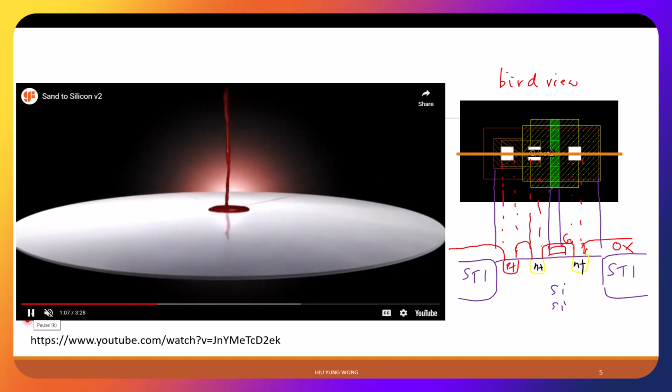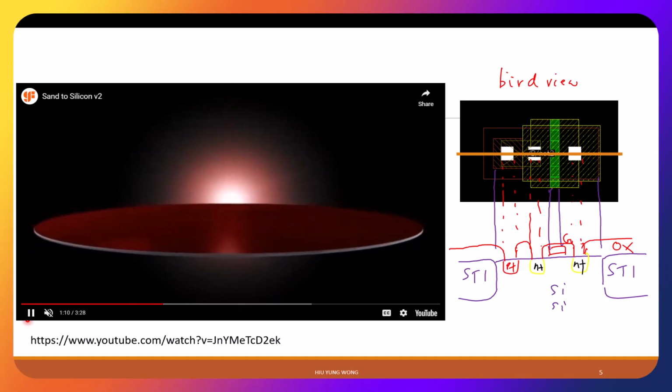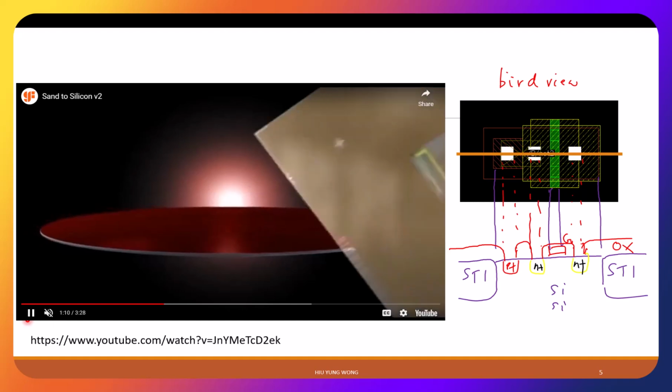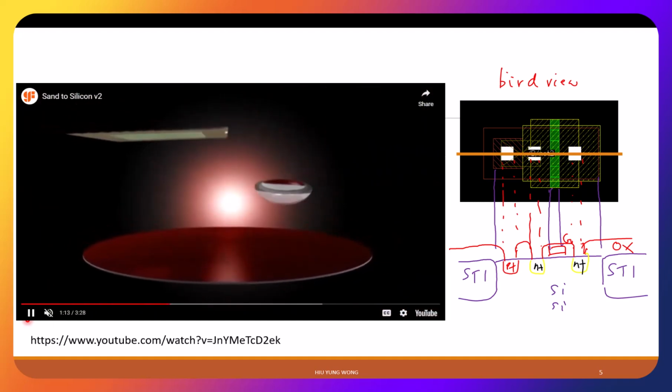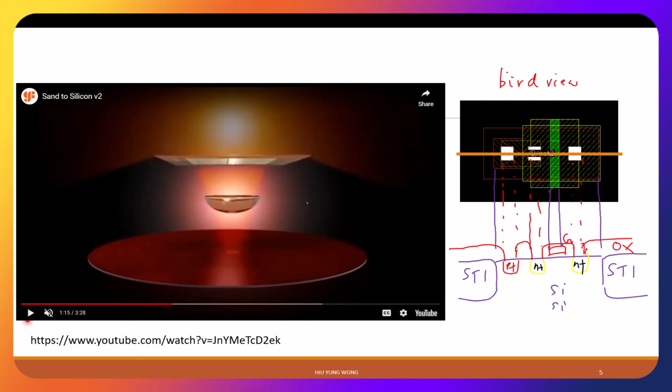Now, in particular, it shows the lithography process. It drops some photoresist, which is liquid, and then spins the wafer very fast, so you form a very thin layer of coating. After you form the coating, you see on the top this is the mask. This is what you design. For example, I want to draw some holes here, 3 holes. This becomes a part of this mask. Then you have a laser light source going through this mask and an optical system, and you form the image on the photoresist. The photoresist is light sensitive.